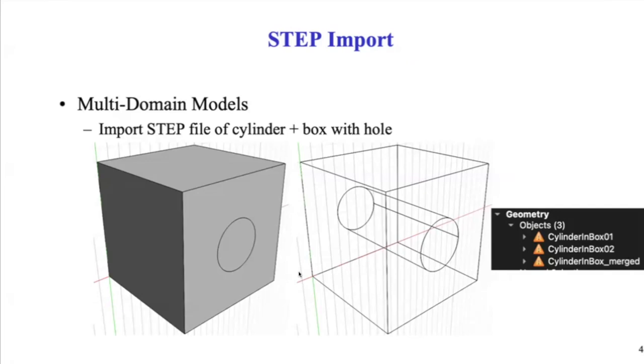What happens is when you export it to STEP, it remembers that your geometry started from a cylinder and a box, but by default, it would actually create two separate geometries. So when you mesh them, there's no contiguity of the mesh. The mesh will not be continuous across this interface, for example. So it turns out that there is a capability, and we discovered relatively recently, to merge the two geometries that are imported. And when you merge them, now you have the choice of either meshing this and this separately or this one. So FEBio Studio will automatically import the two and merge the third one.